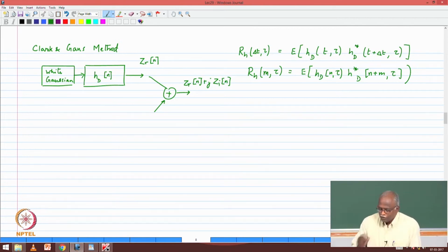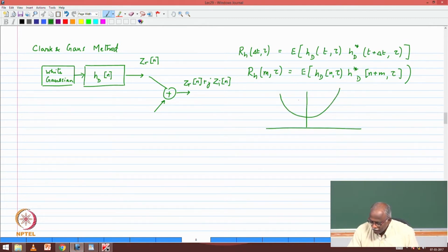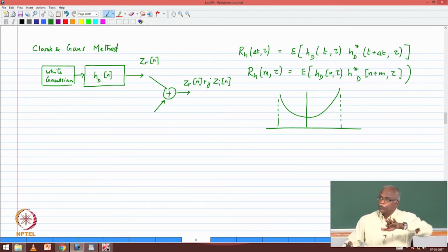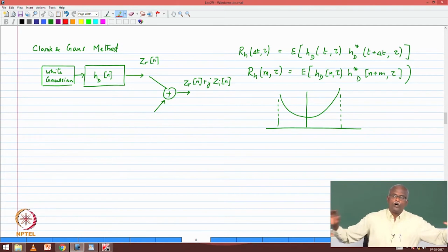Okay, first observation that I want you to make is, can you tell me something about this filter? What can you tell me about the impulse response of this filter? Real, that's correct. Very good. Anything else? It's a very sharp filter. Look at how steep it falls, basically. So when you have very sharp filters, what is your impulse response behavior? It will be very long. Okay, so which means that in order to generate a reasonable sampling or representation of the signal, you're going to have to filter a lot of data before you can get a usable segment of information.